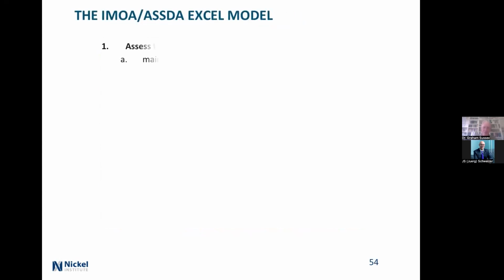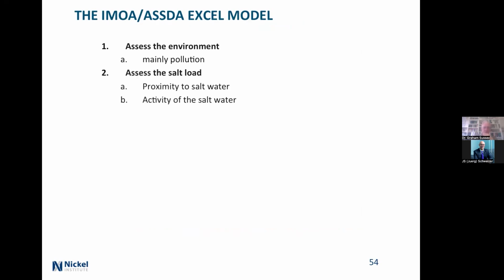Okay, final bit. There is an IMOA ASDA joint thing. It's on the IMOA website. And you assess the environment, mainly pollution. You assess the amount of salt separately. So you look at where you are in relation to the sea and how much activity there is. It's an onshore wind? Yep, more activity. Rolling surf, even more activity.